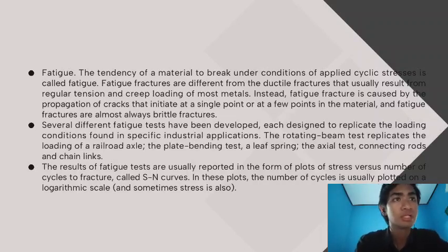Most parts and fatigue specimens contain points of stress concentration, such as surface roughness or changes in the section of the specimen, at which stress is concentrated. When fatigue cracking initiates, the amount of concentration can be determined and is reported as the theoretical stress concentration factor, or simply the stress concentration factor.